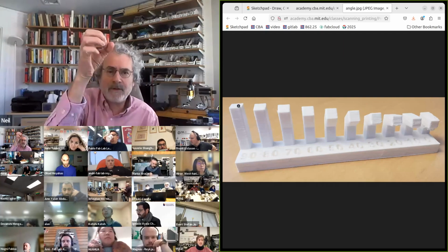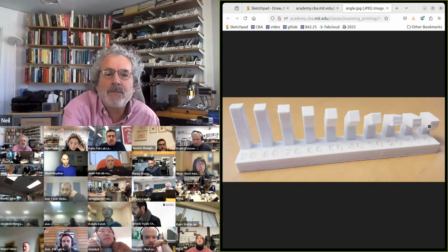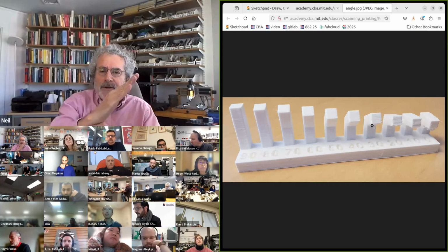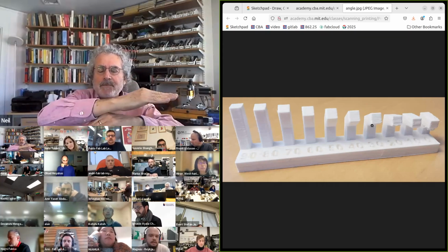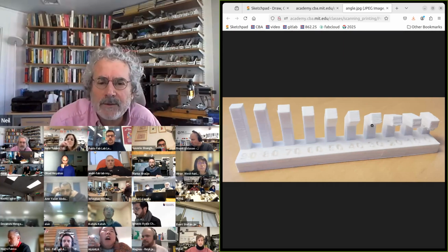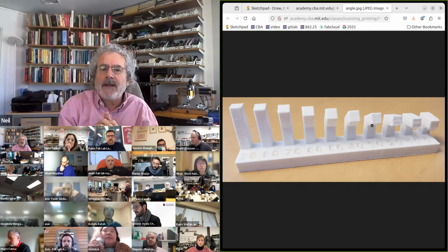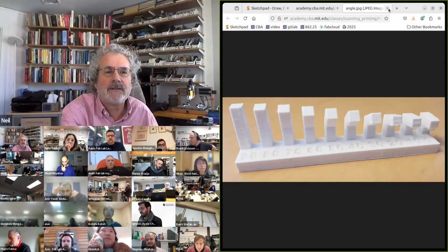Straight up builds just fine. If you go straight out without supports, you get spaghetti underneath. But if you look at the angle, when you get to about 30 degrees, each layer can build on the next layer. So a 30-degree angle, you can print without supports. And so if you use that as a design rule and you don't have flatter angles than that, you don't need supports.